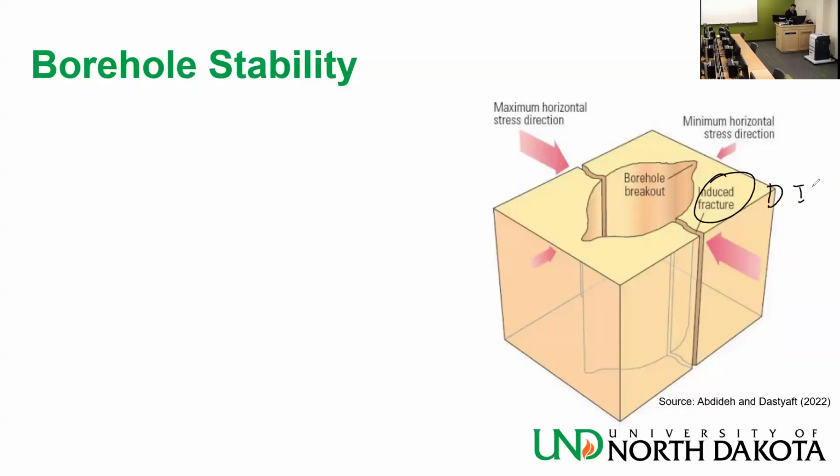DITF, drilling-induced tensile fracture, is basically a mode 1 fracture, and it's the same DNA as the hydraulic fracture that you are doing in stimulation. And it's the same DNA as the underground blowouts that we learn to be afraid of in drilling. Same exact DNA. If you are trying to model them mathematically, you are going to do it the same way. You are going to use that tensile failure criterion I mentioned earlier in the previous slide.